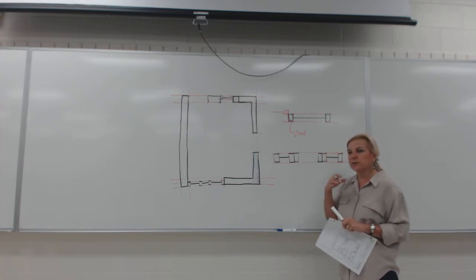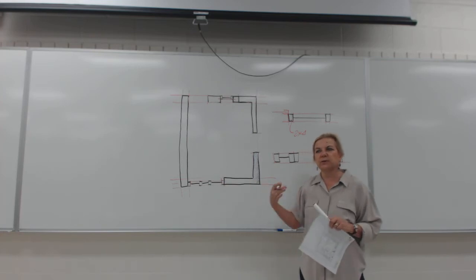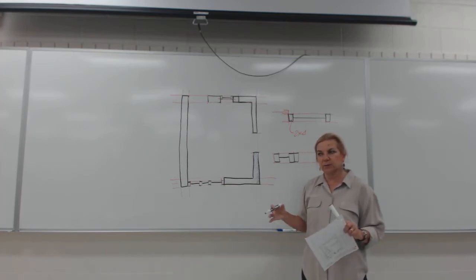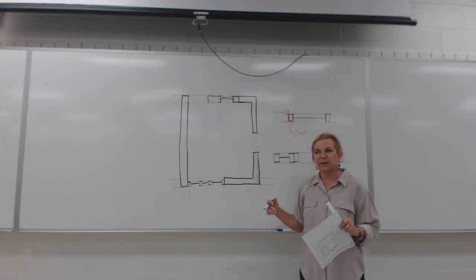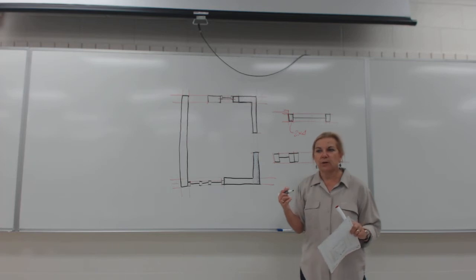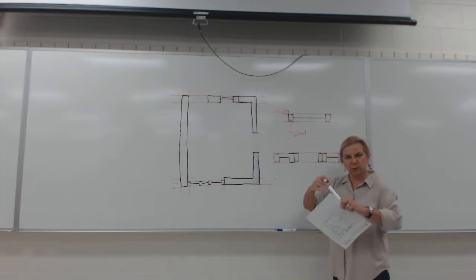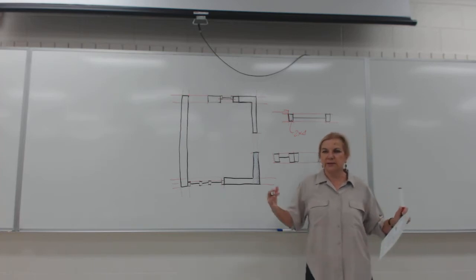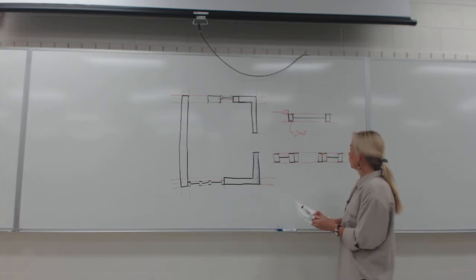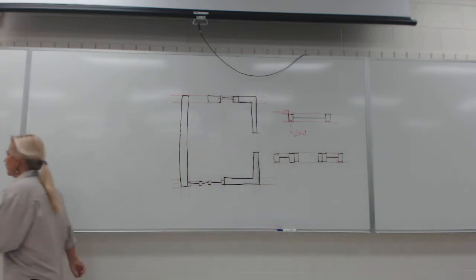The door needs to open to the house, okay? We don't open doors to the outside. We always open exterior doors the way the threshold and the whole thing is built, we open it to the inside. Imagine that you have a pile of snow on your porch. You'd have to plow it through. So the screen door opens to the outside, but residential door, we buy already installed into the frame. They would be opening to the inside.